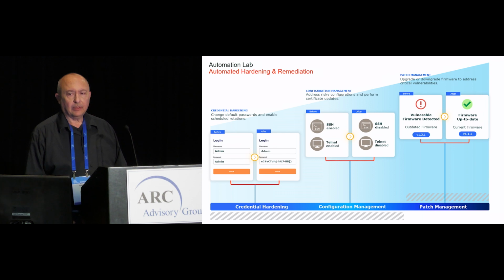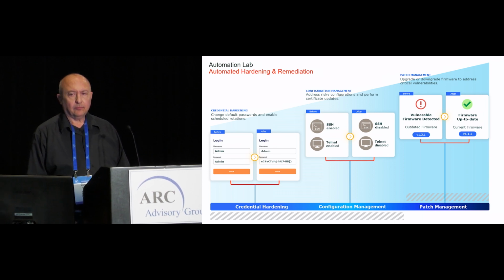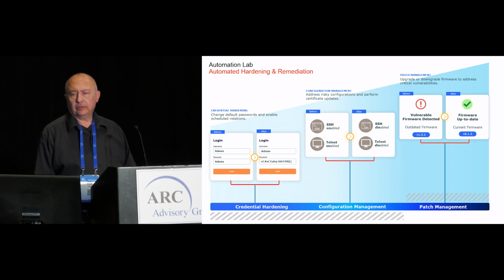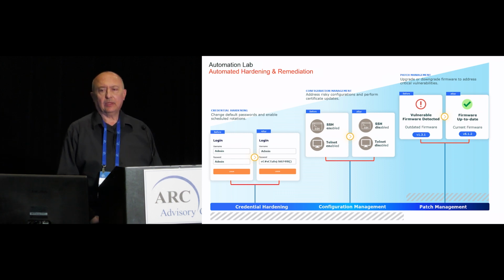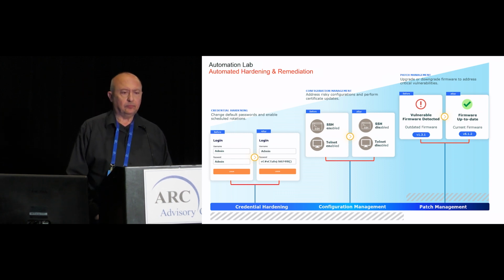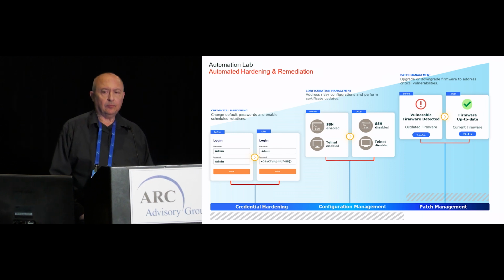Hello. I just wanted to comment, James, rather than ask a question. I'd like to be able to answer the SL question or the target level question. IEC 62443 describes zones and conduits, and from a zone perspective, you would take your devices and break them up into those zones, and then at that point you would assign a target level from 0 to 4.